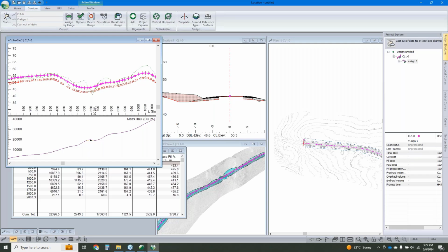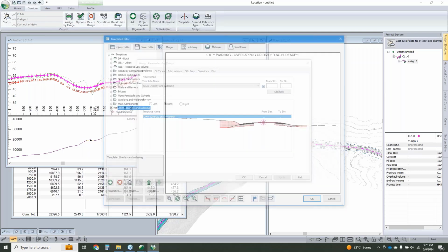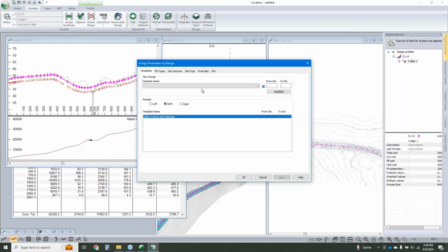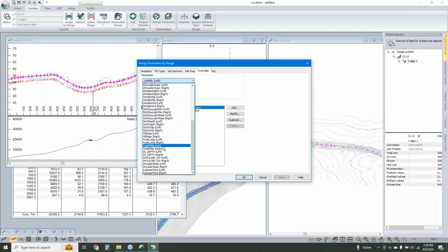The other way would be if you're referring more to how deep your notches are with the sub-base material getting added in. We absolutely could, and we can tackle that a few different ways. One would be to make an entirely different template, with a different value for the materials making up that notch. Two would be to override the existing one.